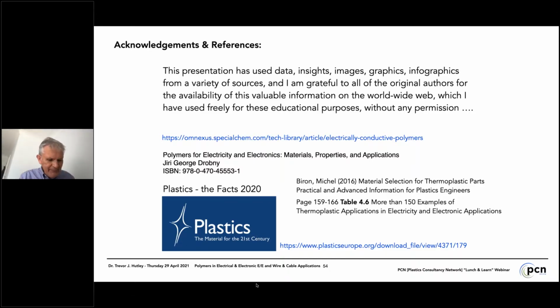Well, thermoplastic materials is one of the primary classifications of polymer and plastics materials. Thermoplastic materials are those which can be melted and processed and then solidified, and then they can be remelted and reprocessed and resolidified. Whereas a thermoset material is a material that can be processed by heat and pressure, but then a chemical reaction takes place which makes it stay in that shape or in that structure for the rest of its application life.